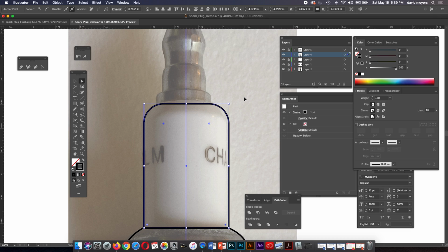Okay, so what I did, to make that curved at the same time, because otherwise if I just have it like this, it's going to do it to that. If you have the whole thing selected, and then you go and do this, it'll do it to all of them like that, okay? So what I did was, I got the direct selection tool. I selected one anchor point there. I'm going to select this anchor point here, and then I'm going to just pull that in, just like that. That is so cool how that makes that.